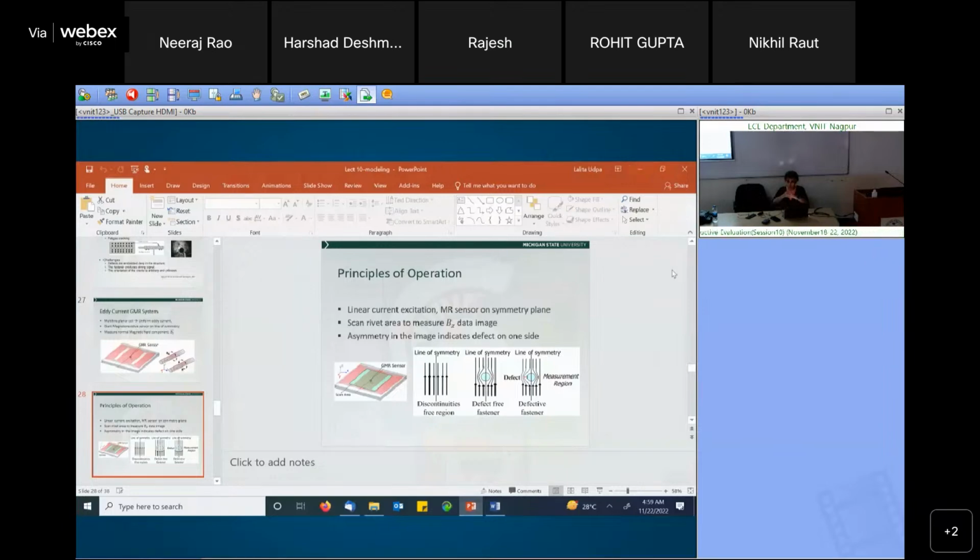Because the rivet produces a discontinuity. Wherever there's a rivet, there is a hole and then there's rivet material, so there is some air around it. So it's a discontinuity. Okay, now I understand your question. It's all aluminum, but sometimes they can be steel or sometimes titanium too, in which case clearly there is a different material. But even when it's aluminum, it produces a signal because there is a small, very thin air gap.